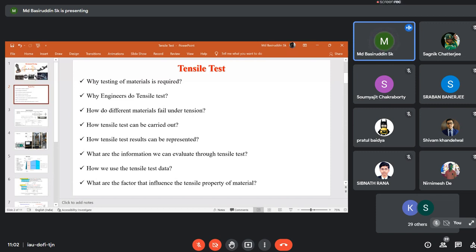quite comparable results. But in other cases, if you don't follow the standards, of course your load will vary, but due to the constraint effect, your stress may also vary. So for the same material, if you fabricate two different specimen geometries without following the standards, then the stress that you report for a particular material may vary.